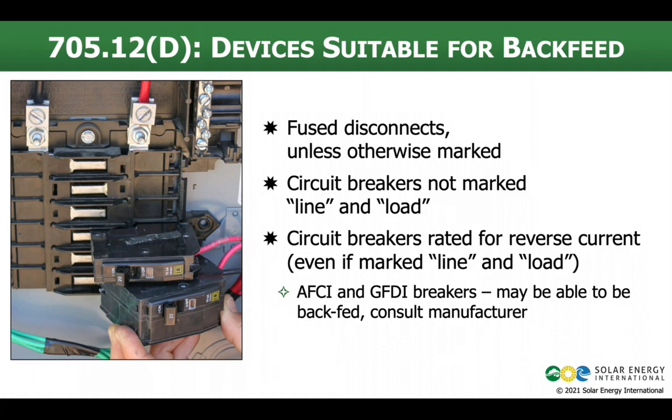We've seen this over and over again, particularly with ground fault breakers. Some large services, the main breaker is a ground fault breaker, and it has a line and load marking on it. But the manufacturers have done the testing, and their product is okay for backfeeding. It may not be obvious. You may have to dig down and find that. And if you just look at the line and load, you might say, oh, I can't do this.